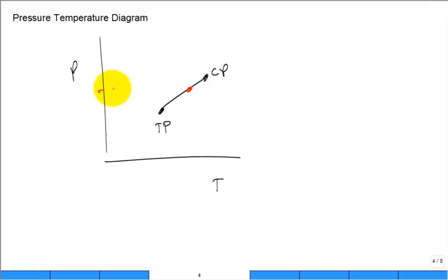You immediately drop the pressure. Where does it want to go? It doesn't want to go from liquid. It wants to go into the vapor state. But you can't break those molecular bonds without supplying some energy. But it's like you take out of one pocket into the other pocket to get it back over to the two-phase region. But that two-phase region will be at a lower pressure, but it'll also be at a lower temperature.